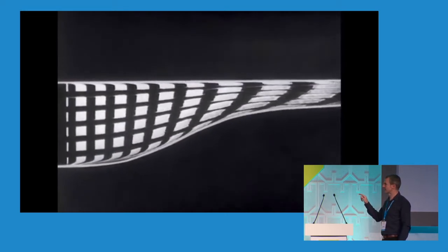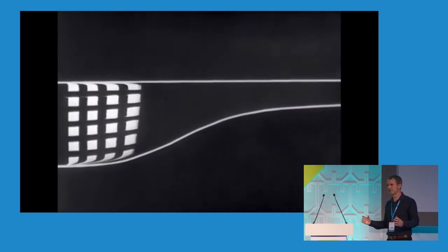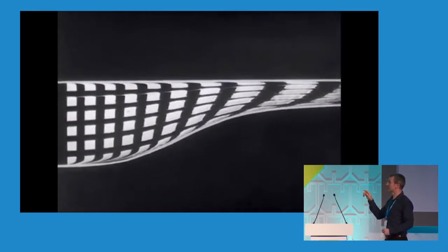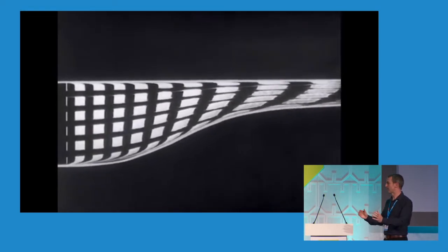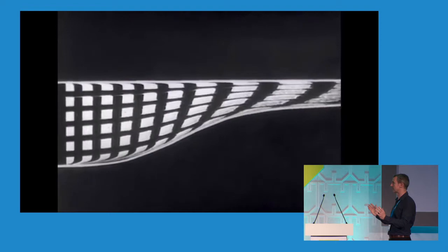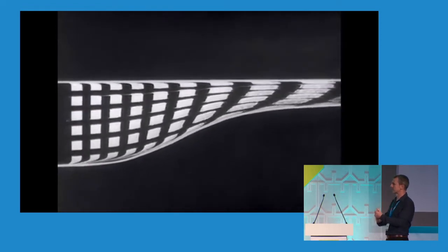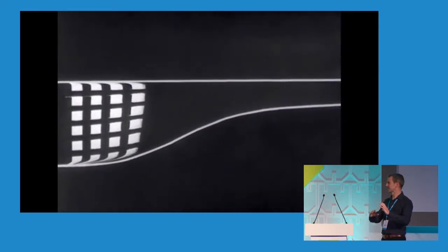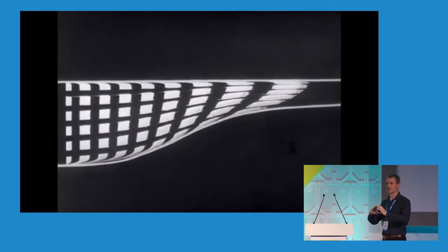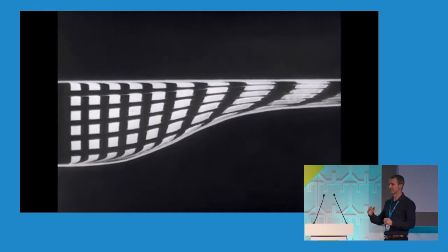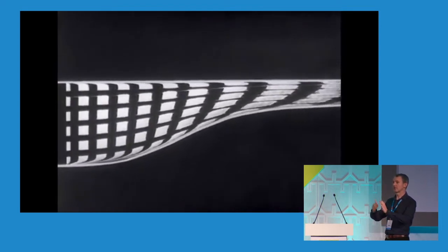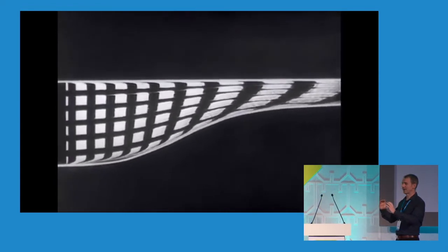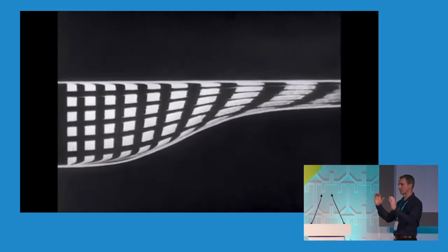And this is a really interesting observation, because if this tells us that's where the losses are coming from, then obviously the internal surfaces of that pipe have a really important part to play. Not just the surface friction, so how smooth that pipe is, but just the amount of it in contact with the flow. Now, I'm sure many of you will remember that if you halve the diameter of a pipe, through the constant of pi, you get half the circumference. So there's a pretty linear relationship there. But if you halve the diameter of the pipe, your cross-sectional area goes down by the square of that. So you start to lose your capacity at a much greater rate than your wall section comes down.